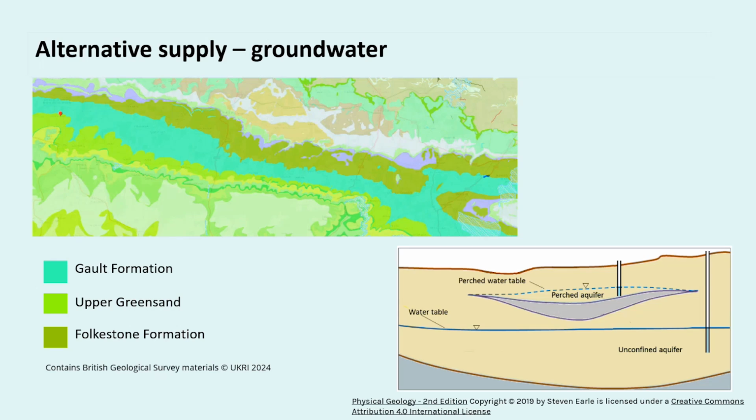So it can take upwards of 1 year or more to obtain this information to accompany a planning application. And so early commencement is critical. And it isn't cheap. A project to sink 3 exploratory boreholes just to confirm whether water is available and in sufficient quantity and quality would cost in the region of £600,000. And we've got a project that is currently using that approach.